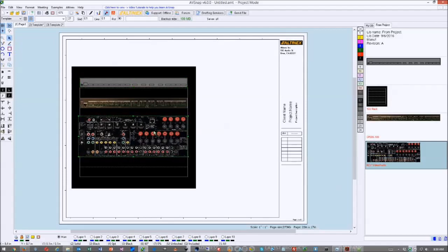It's mainly used when you have symbols and you run the cables around the symbols from one symbol to the other, and if this cable has an issue, it will highlight the symbol as an error. But if you don't want it to highlight it, you just basically say don't even look at anything, block it completely from analyzing the design.